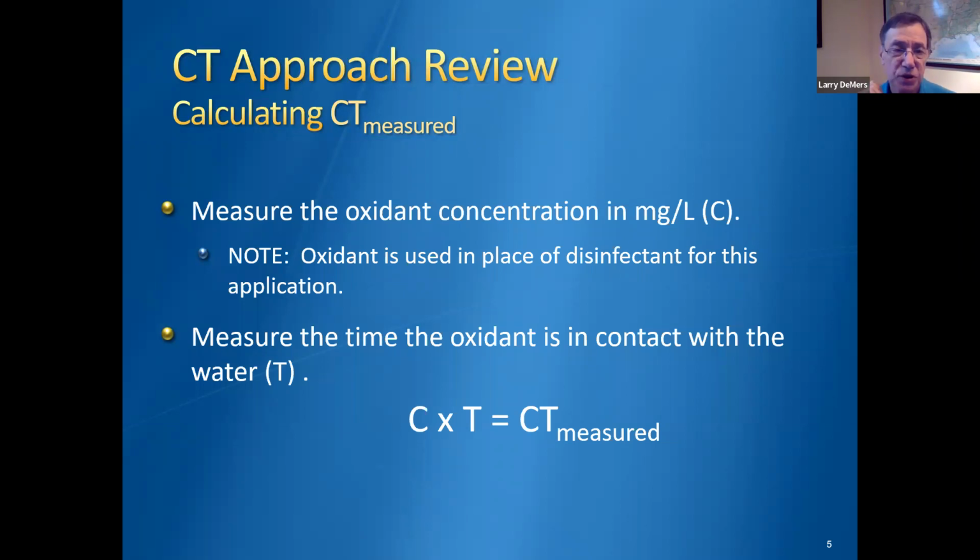Use the same approach for cyanotoxin destruction using CT as you would apply it for pathogen inactivation. So all of the rules, all the guidance, all the guidelines for CT for pathogen inactivation, the same ones follow for cyanotoxin oxidation.